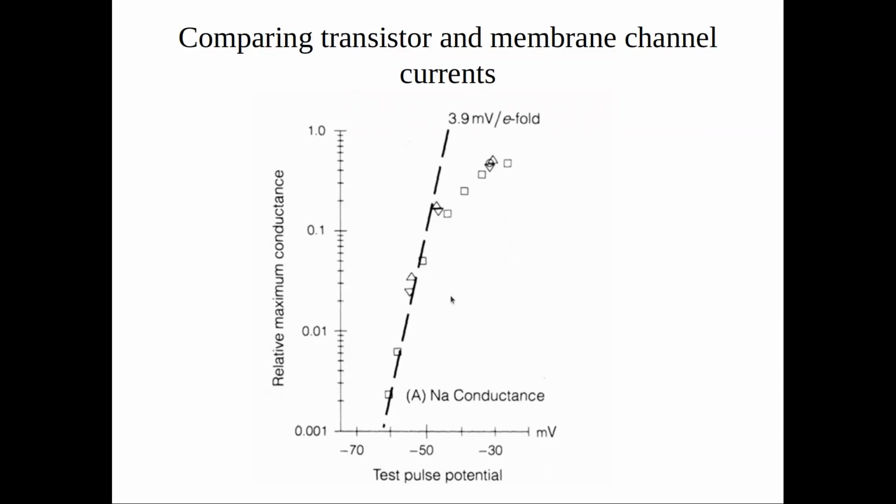So also in this case, we have exponentials, and you can imagine the reason that you have flow of sodium from inside to outside is because the concentration is changing. As the concentration is changing, you have more or less flow of sodium. This is to show you, if you plot the subthreshold flow of current through the transistor channel, not the protein channel, you have much less gain. And in computing systems, gain is power. The more gain you have, the more robust you can be to noise.